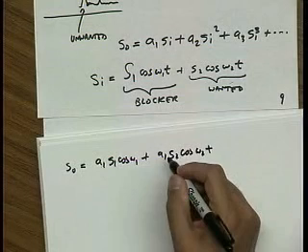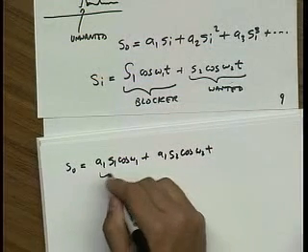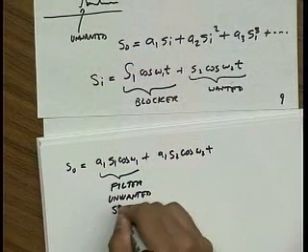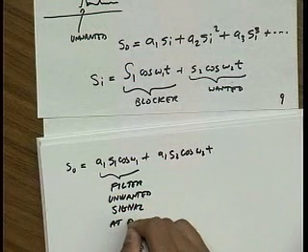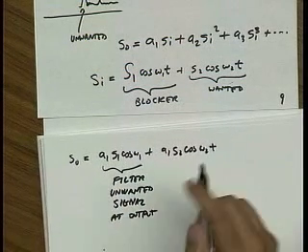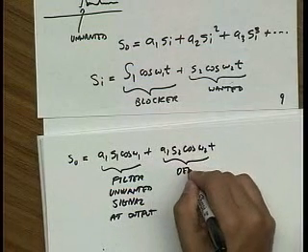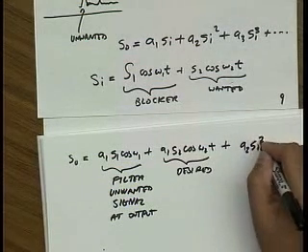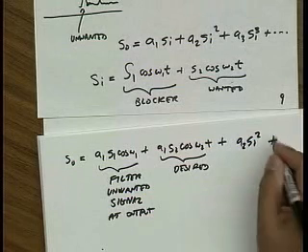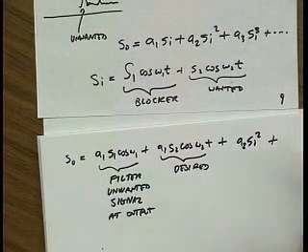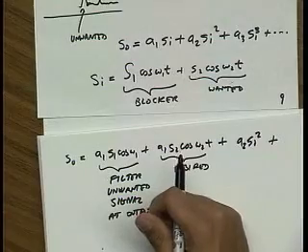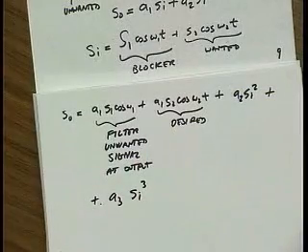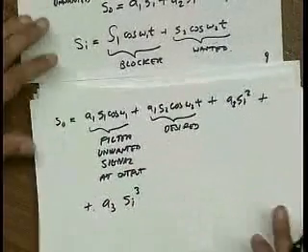But let's say that's not an issue because I'm going to filter this out. This is the desired signal that comes through. And then I'm going to have basically square products. This is going to lead to IM2 tones, right? But again, let's assume I can filter out my IM2 tones. And then finally, I'm going to get this cubic term. And what I'd like to show you is that this cubic term generates all the nasty stuff.